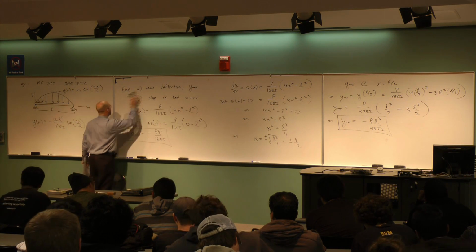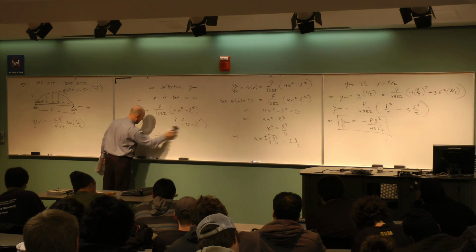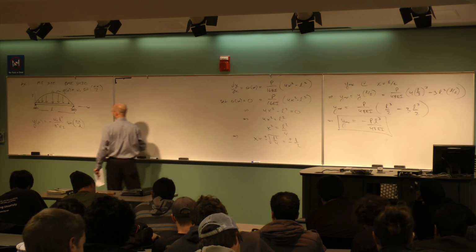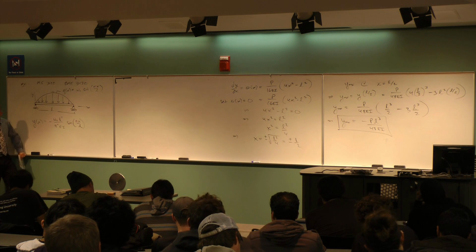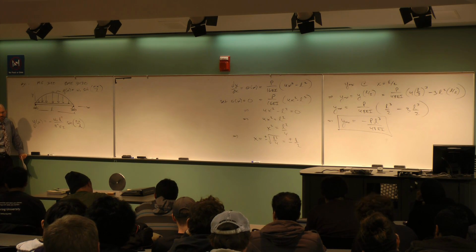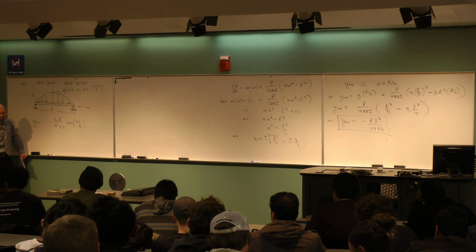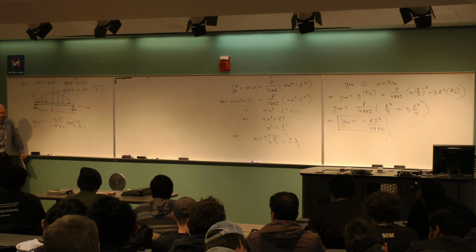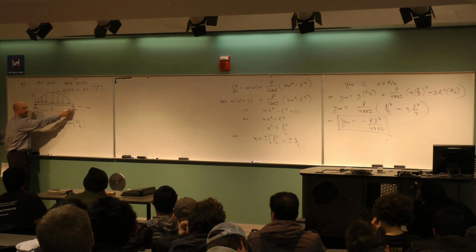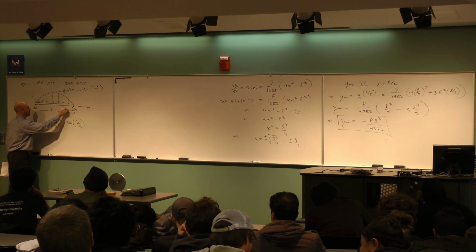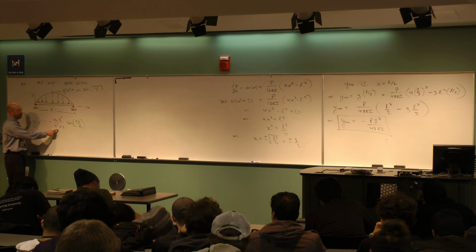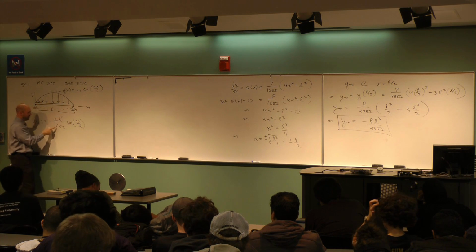By the way, what kind of function is that? What's it going to look like? It's a sine function. How's this sine function different than this sine function in terms of the way it looks? It's going to be negative. So what does that do with the way it looks? It flips it upside down. These beam problems are pretty intuitive. Here's a load. What's the beam going to do? It's probably going to do something like this. So it's a half sine function the other way, flipped upside down. The amplitude obviously is a different number than this. This guy has units of what?